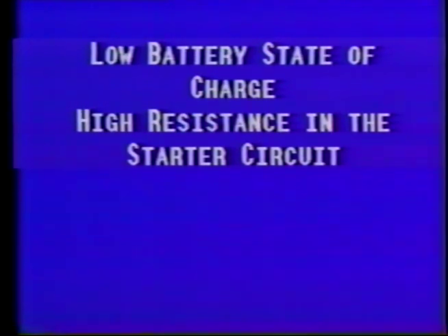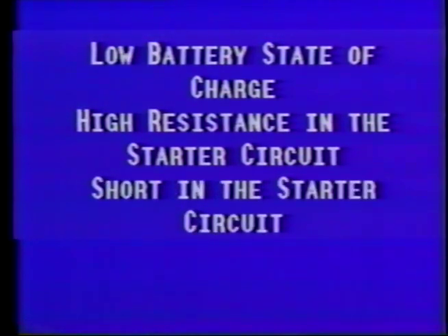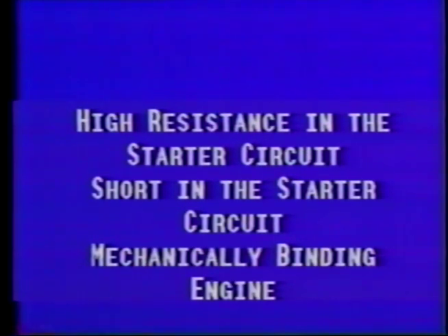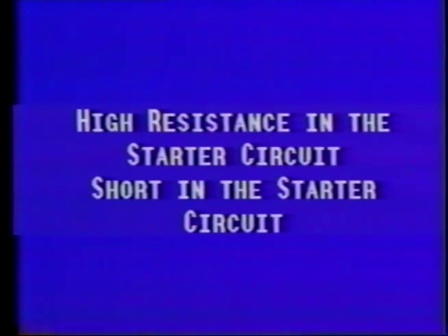The second possible cause is high resistance in the starter circuit, not allowing sufficient current to the starter. The next possible cause is that there's a short in the starter circuit, and the last possible cause is a mechanically binding engine. The low battery state of charge was eliminated by the load test, and a mechanically binding engine was not even given as a choice.